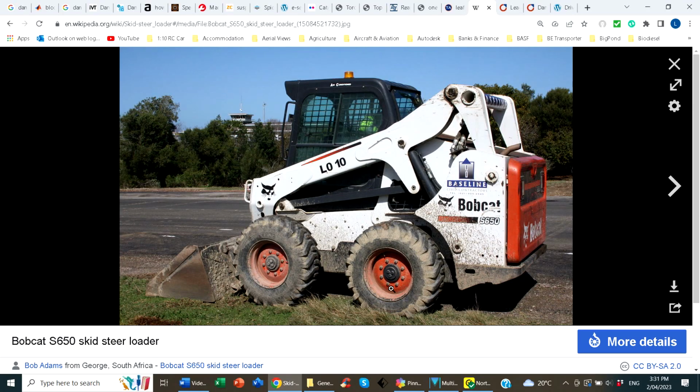And that might be fine for working in soft conditions off-highway. And I'll give you another example of where it's fine. Here's one that we all recognise, Bobcats. No suspension, don't need it. It's a short wheelbase machine operating in soft ground typically, so suspension is not a priority. But you may have trouble at speed as a result of lack of damping.